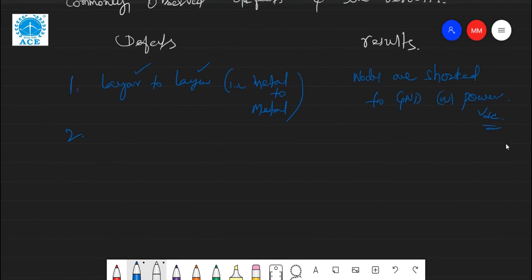So the second one, disconnections. I can say mismatches and disconnection of wires. In this case, what will happen here? Basically, disconnections means open circuit, whether they are connected to each other or open circuit. Okay, so it becomes open or shorted to each other.